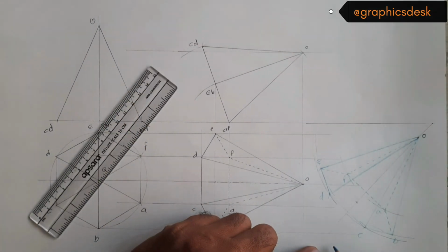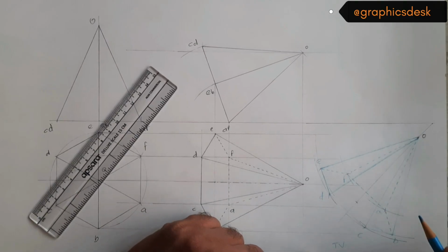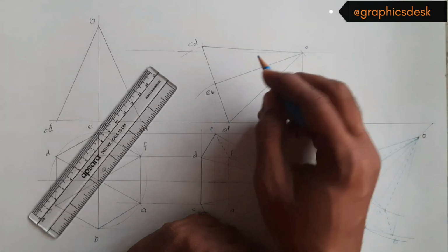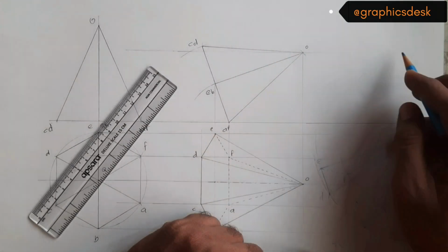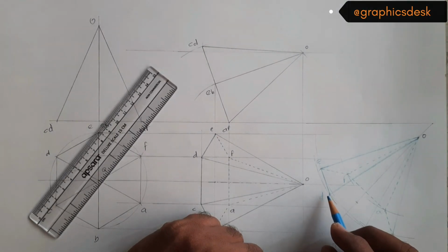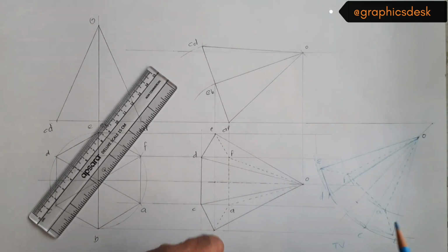Now this is our final top view, and that is why it is in blue. Now let's draw the front view in a similar way. So we'll be carrying the projections from this particular front view over here, and we'll carry the projections vertically from the top view to locate the front view above XY.